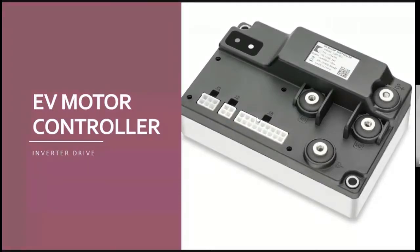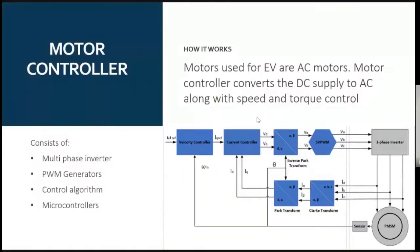Here is an example of a motor controller. This is a packed controller for EV application. This is an EV motor controller with inputs and outputs. All are packed, and there will be a communication system. This is shown just as an example. It is used in EV applications. It's a basic motor controller block diagram. There can be a velocity reference, meaning a speed reference, and that will be converted into a current reference. There will be a current controller.